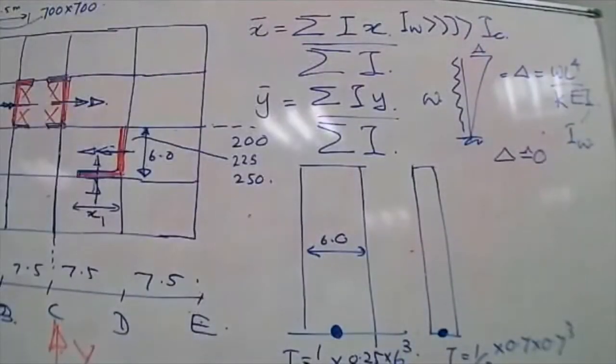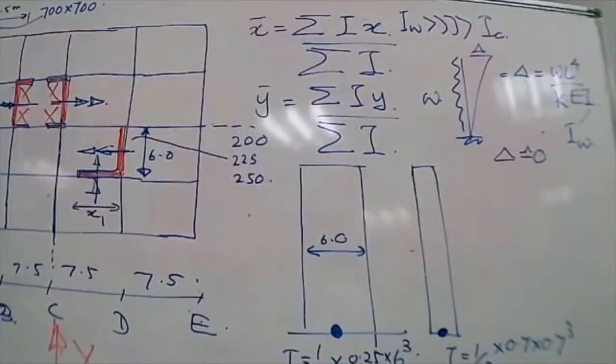So if there's no lateral deformation, we will have about 10-15 millimeter deflection because it's a 40-meter tall building deflecting 10 millimeter, very small. So we say building is not deflecting. Building is not moving. So if the building is not moving, why? Wall is not allowing it to move.